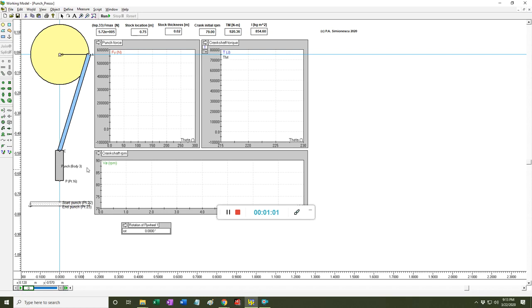These points, together with the velocity of point 16, or rather the velocity of the punch in the y direction, serve to define the conditional force that simulates the resistance to punching of the workpiece. These are controls, and I have one where I can edit the maximum force at the beginning of the punch, calculated as you know, the shear area times shear strength of the material.